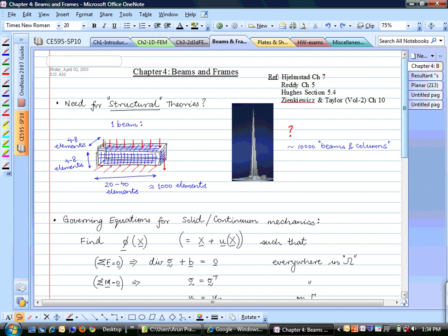In that case, the pin is modeled as a rigid body. So you can create a rigid body as a pin, and then study what stresses it creates between the holes. If you put the holes close together, how much does the stress increase?